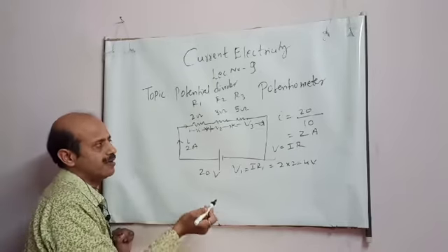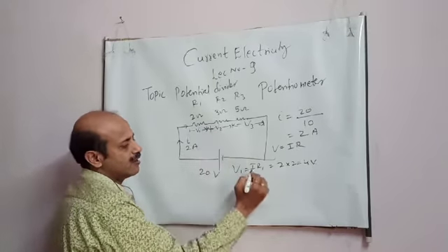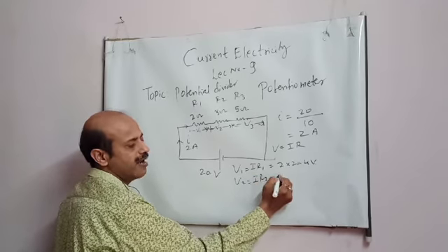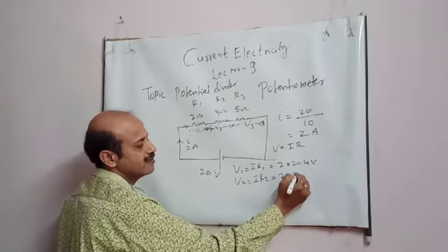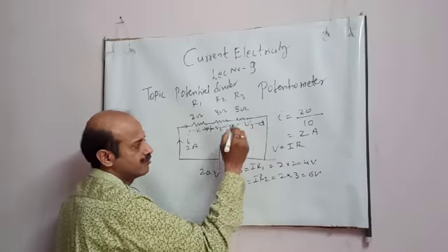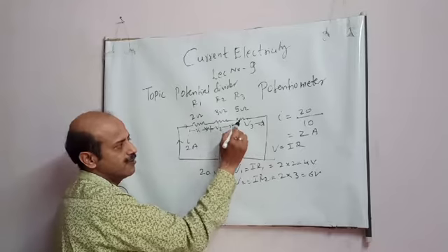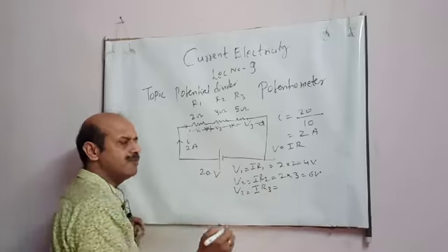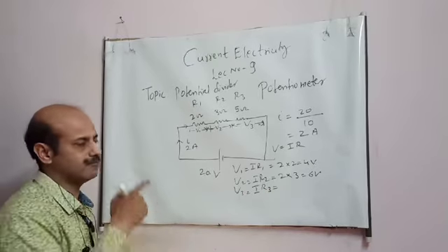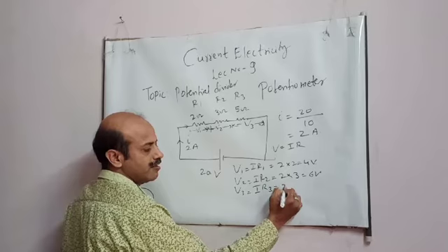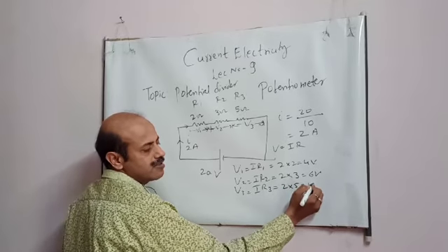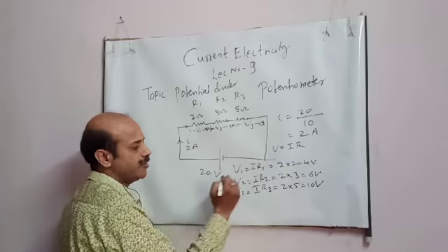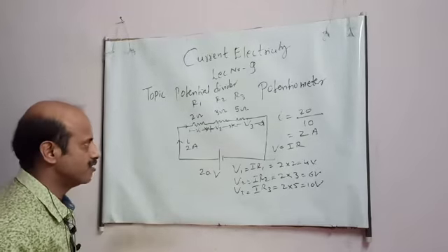Now further, how much is the potential difference across this? It is IR2, student. I is the same in a series circuit, so V2 is 6 volt. This is 4 volt, 6 volt, and here is V3. I want to come to a concept by explaining you this. IR3, 2 into 5. This is 10 volt. So 4, 6, 10. Total you see 20.